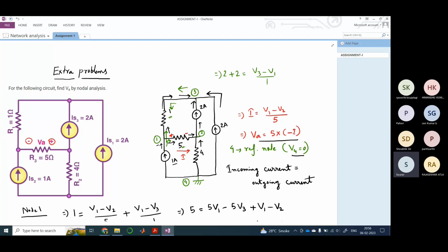Can we do that? See, you can always practice that at your own time. I think it may be valid because the 1 ampere current source is not dependent on the 4 ampere source. So you may directly apply the potential divider rule here and then find out the current flowing through the 1 ohm resistance, right? Yes, you can do that.